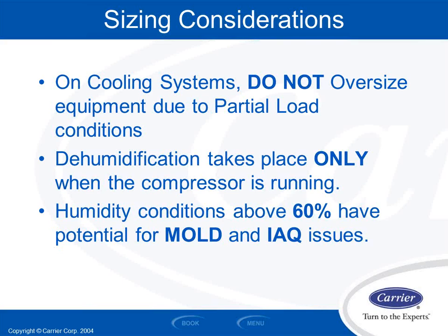What that equipment will then do is turn on the least amount of stages possible. So on a 2-stage unit, it'll turn on first stage only. On a 5-stage unit, it'll turn on first stage only. And then I'll slow the blower down that moves the air across the evaporator, slow down the supply fan to increase the amount of time the air is in contact with the evaporator coil, which helps me pull more moisture out of that air, right? So I can do those kinds of active things to help dehumidify when I have more extreme scenarios.